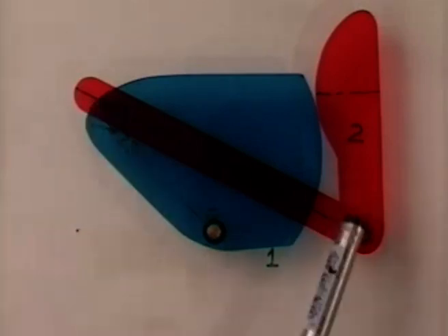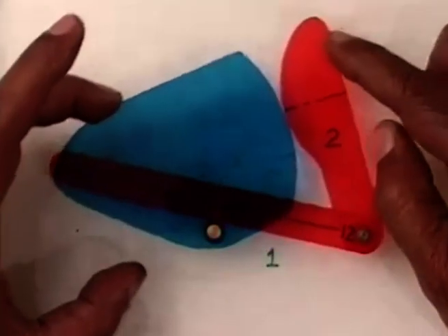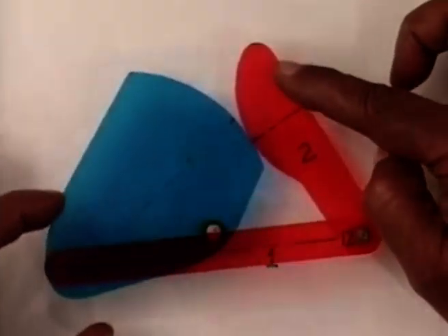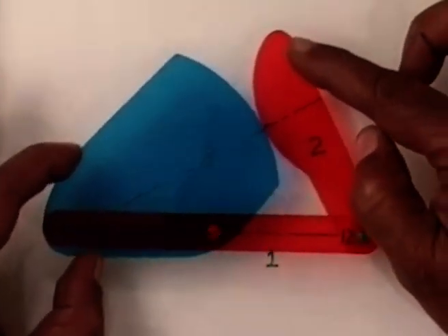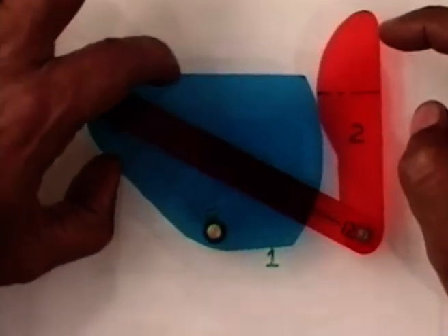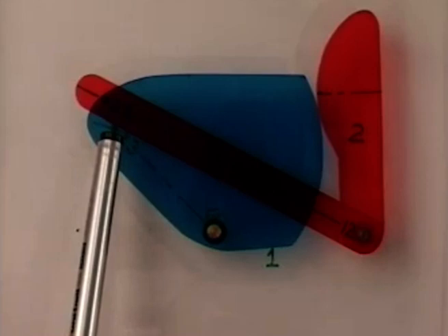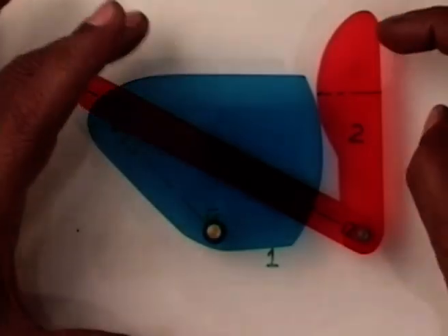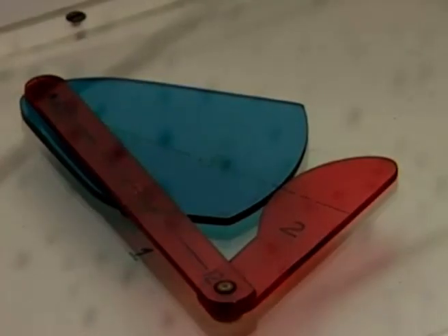This is the point 2, 3 on body 2 and this is the point 2, 3 on body 3. At this location, at this configuration, their velocity is the same. So around this configuration, they move almost with the same velocity. At this instant, with exactly the same velocity, around that region, almost the same velocity, so there is not much separation. However, when they have moved a lot, as we see, that point 2, 3 which was here as a point of body 3 has come here and as a point on body 2 has come here. I hope this clears both the concept of relative instantaneous center and the application of the Aronhold-Kennedy theorem, which we shall